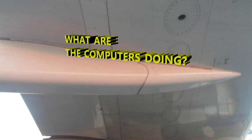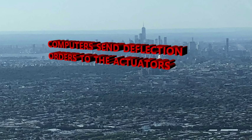All right, digital network, you've got your COM and your MON buses, your buses for command signals, and then your MON buses for monitoring. So the computers are doing what? Okay, they're sending those deflection orders. This is all based on aircraft data that they're getting from different sensors.